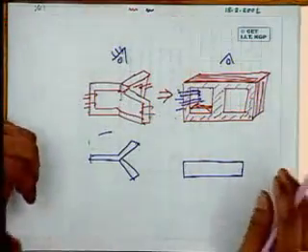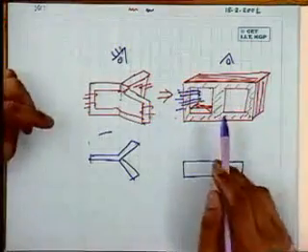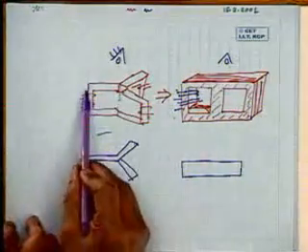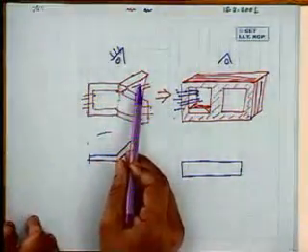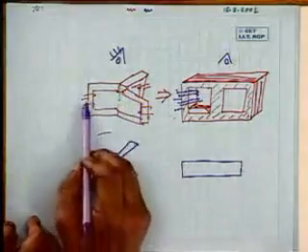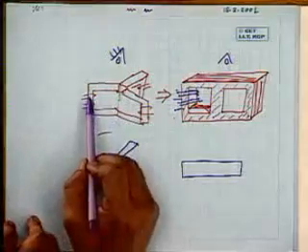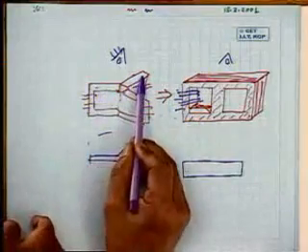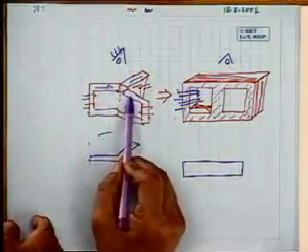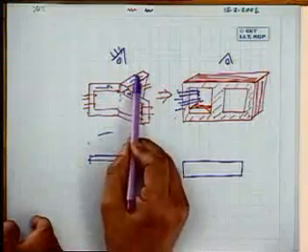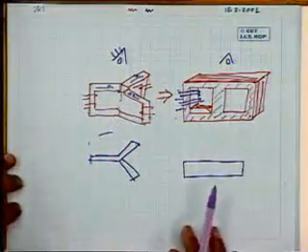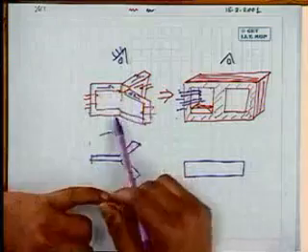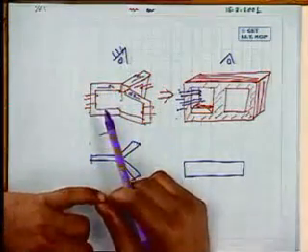Now what you sacrifice in order to get some simplification in the construction, that I want to point out. In this case, if a 3-phase transformer is constructed in this manner, then you note that when you energize it, suppose no load condition, each winding will produce its own flux, phi A, phi B, phi C, like this. Now the reluctance of the path through which each of the fluxes flows are equal in nature. But here it will not be like that.